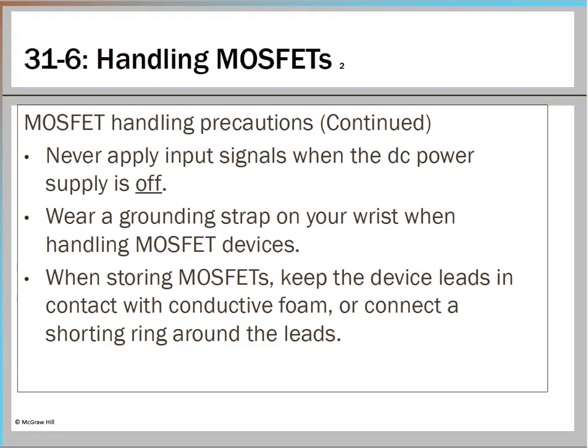You have seen that most of the time when equipment arrives from the manufacturer, it has a foam, and the leads are connected to the foam, which protects the components. In the case of a MOSFET also, make sure that when you are storing it, you connect the leads to the conducting foam.